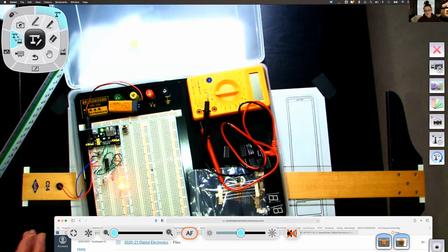The design process at a micro level occurs by designing a circuit, drawing it out, then creating a simulation on National Instruments Multisim, creating a pre-breadboard activity through Tinkercad, and then a breadboard activity through collaboration on their protoboards.